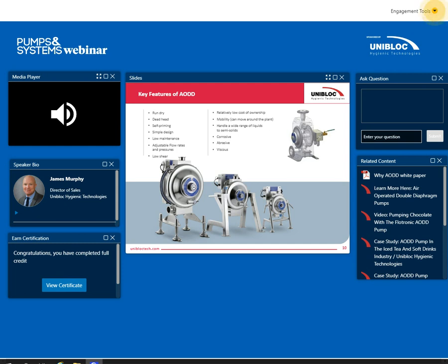So like I said, with a traditional design, that figure 8 design, 30,000 centipoise seems to be about the max viscosity. When you get into one of these center ported type diaphragm pumps that you see pictured here, I've seen it where they can handle applications up to about 150 to 200,000 centipoise. It just depends on a couple of variables such as temperature and the product you're pumping.